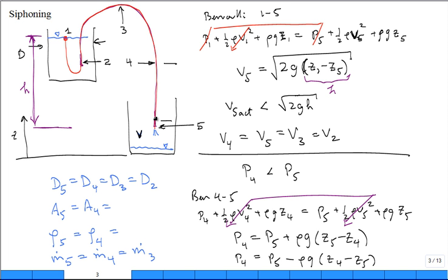It's almost as if it was just fluid statics. Wouldn't that be the same if it was just fluid statics, with no flow in the tube? That's interesting. Now, can you tell me about P3? It's at the highest point. It's at the lowest pressure in this whole system, isn't it? And you can find that by Bernoulli's equation.